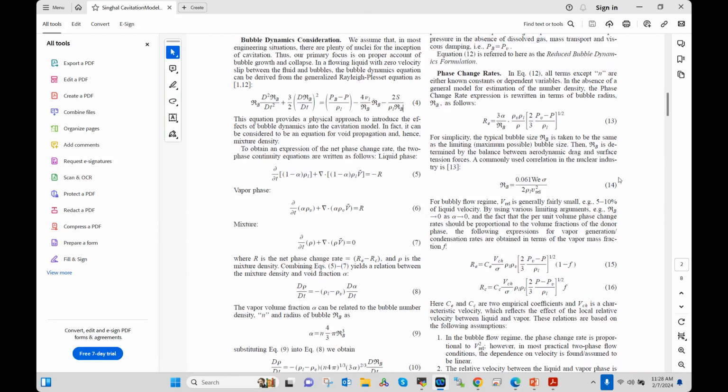The next question from Gabor Lechner is, how is impeller blade surface roughness taken into account in cavitation? Right now we have a roughness on the surface. You can provide a roughness height, but this is not taken into account explicitly. It's just in our flow solver, it'll be a term. So in the cavitation model, it'll be affected based on how we solve the flow field. That's what I would say for this question.